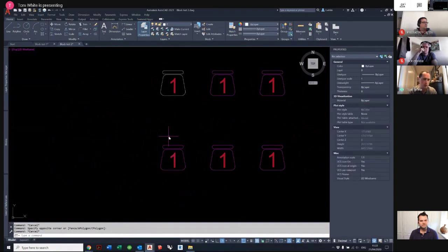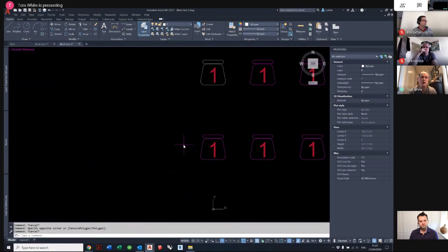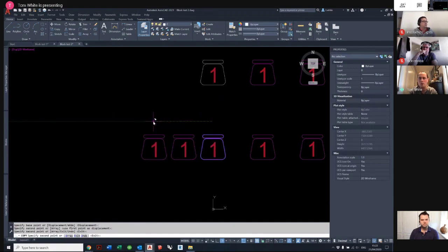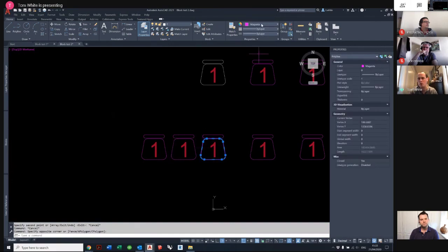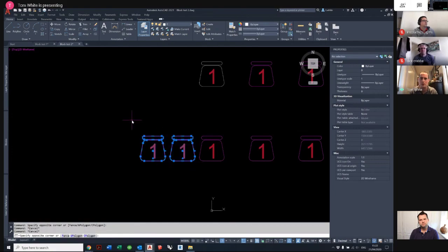We mentioned the DWG compare. That's one thing where it's overwriting the color when you're trying to print it. So in this circumstance, if I wanted to highlight this as a separate color when printing it, it might be quite challenging because the actual element is forced to be on the magenta layer. If I wanted to do a quick print and for some reason print it in green, it would be more challenging than necessary.